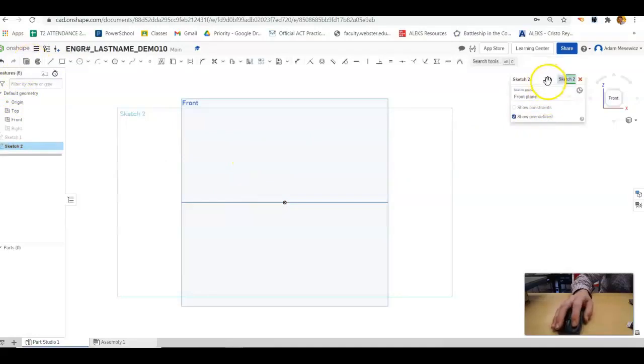I didn't name my first one, which I'm going to go back and do because that's important, proper convention when you're using 3D modeling tools. But this is going to be the face which we are going to actually sweep. So I want to make sure I've named that correctly so I don't get confused if I'm going back and editing. Okay? So like I said, all we need is a center point circle that starts at the origin and has a diameter. So if it says R, that's radius. If it has the circle with a line through it, that's diameter. So we'll dimension this. Either press D or click on the dimension tool, and we'll just make this 5 millimeters.